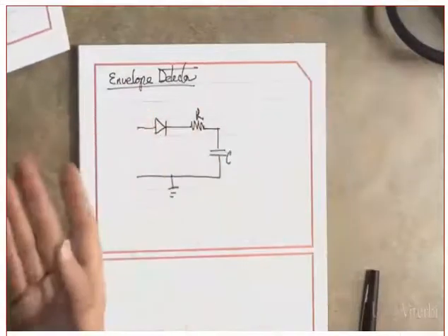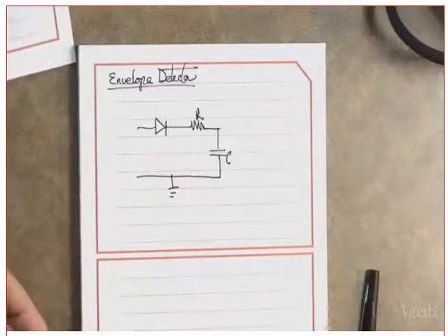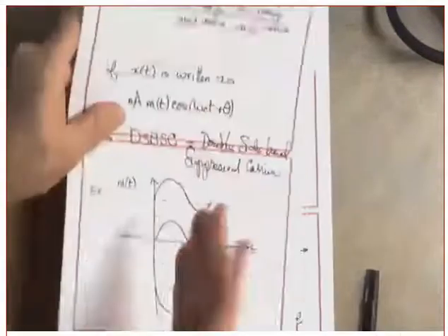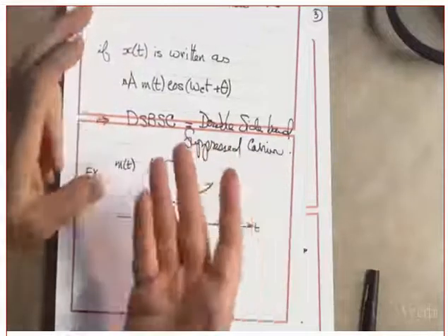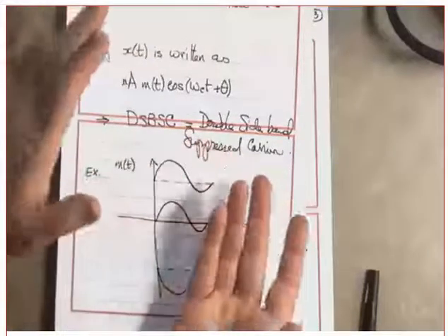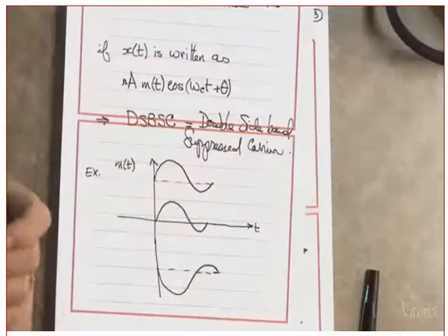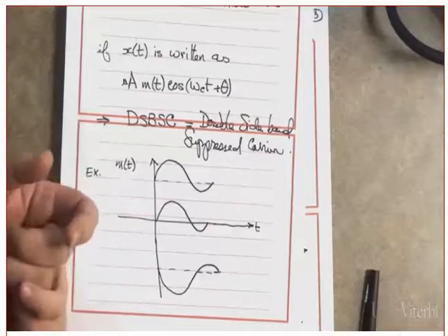This is your AM radios. This is the detector as the receiver. Clear? Now, then what is for DSB-SC? What do I need in here? I need to generate a coherent carrier component at the receiver. Which means I need to have some kind of a phase lock loop. Did you get my point or not?